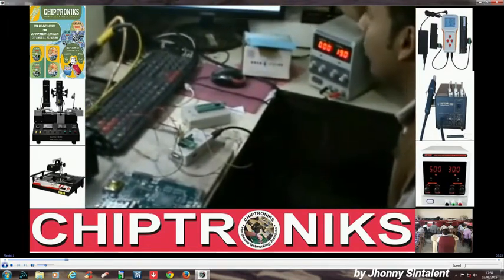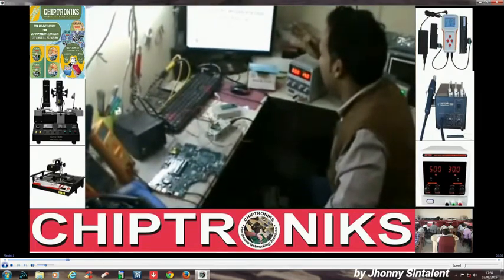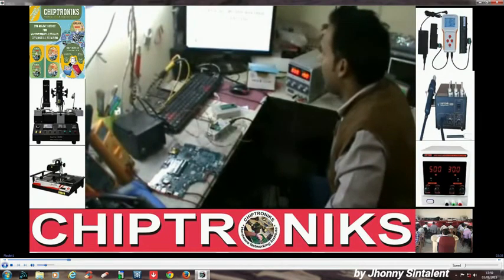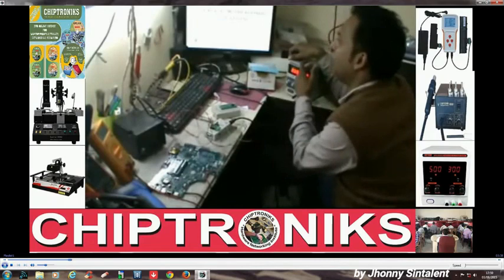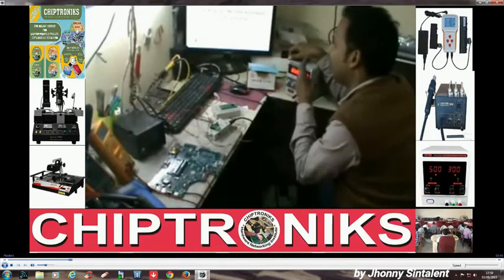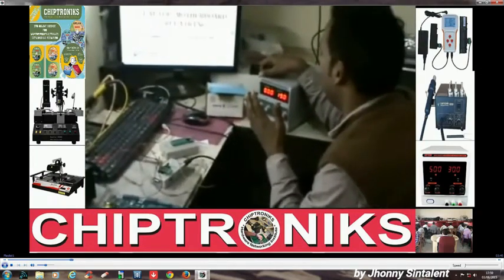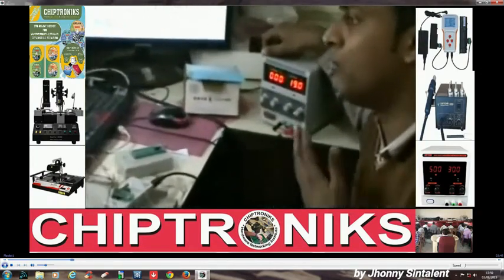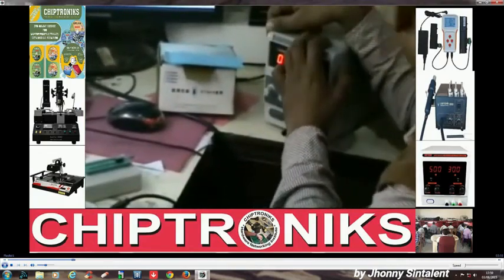After finishing all this theory explaining the IO controller and PCH, I will have a separate class on the current profile, and you can measure the current profile with this DC power supply. Analyzing the current profile will give you a complete view of how the board works. That is also another way to diagnose problems on laptop motherboards. So I'll cover this part once again.